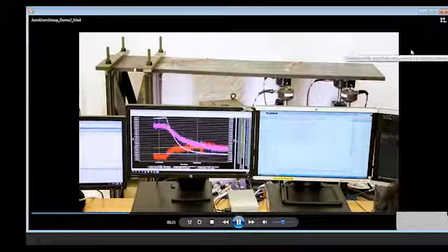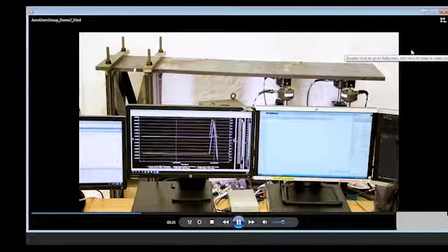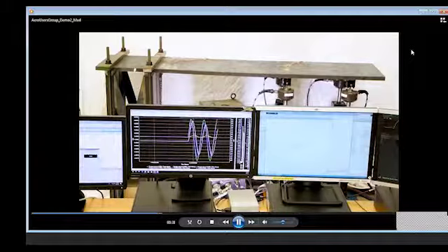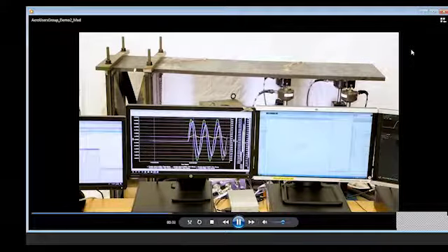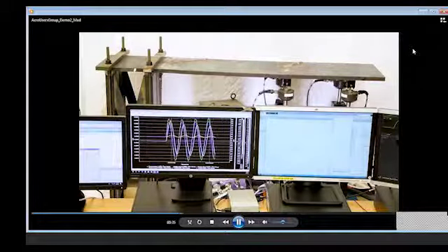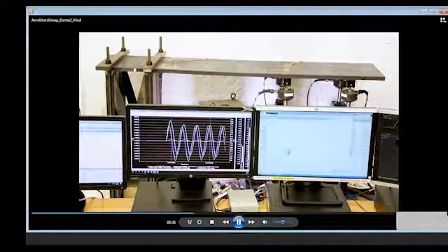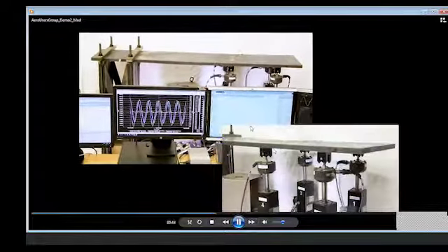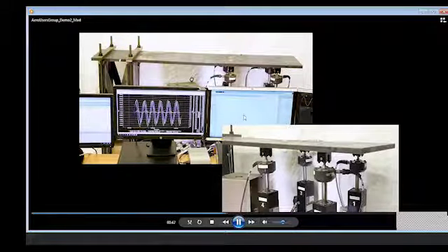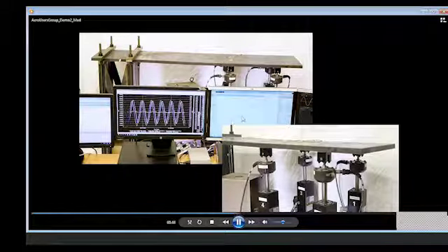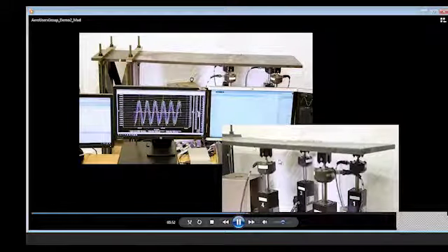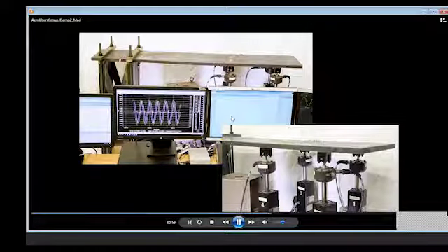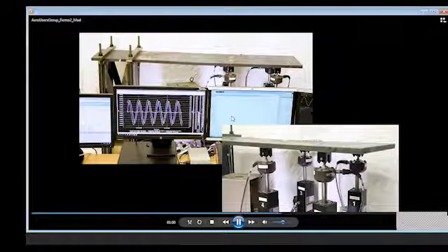Thanks, Paul. So that's basically the testing we did. You see the physical plate being tested over there, and it's very flexible. Here, that's the extended part, modeled by OpenSees. When we solve, we drive this physical rig, and then we start the whole loop. That's the whole cycle of the hybrid simulation, and you see some responses there.